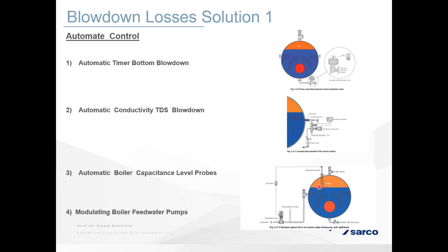So yes, you use more energy on your pump, but you use less energy heating the water in your boiler to steam. As the larger volume is the water in the boiler, I would suggest that the modulating saves more money, even though you're running the pump, because of the amount of volume you're heating.